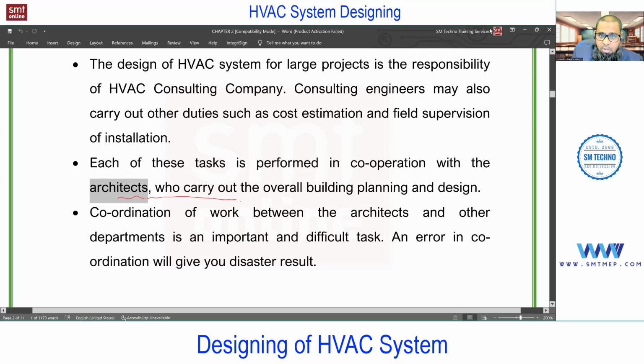And the next point is very, very important: coordination between the architect and the services, and between the services, is a very important and difficult task. And any error in the coordination will give you a disastrous result. For example, if you talk about the design side, before completing the electrical design, if the HVAC people complete the design, then what will happen? I'm talking about the placement of air terminals, duct routing, etc. before the electrical. So what issue will arise?